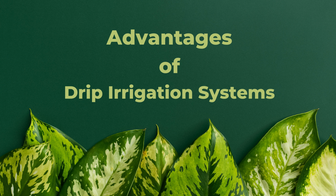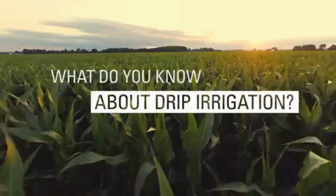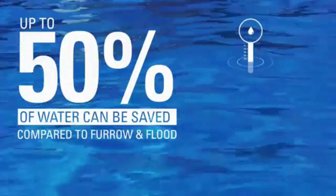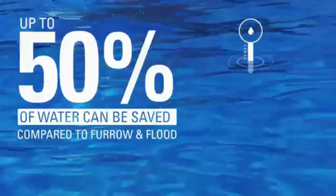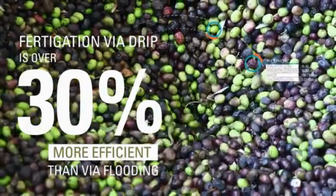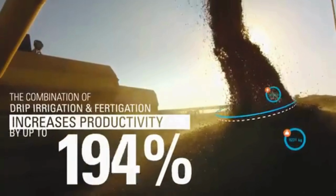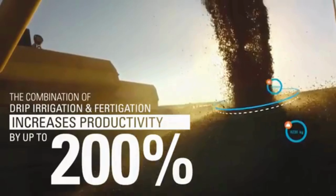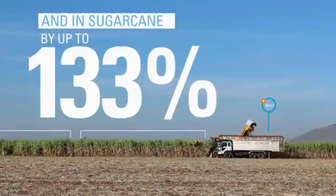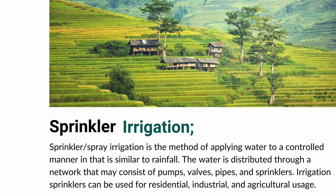Now you can see the advantages of drip irrigation systems. Up to 50% of water can be saved. Fertigation via drip is over 30% more efficient than via flooding. The combination of drip irrigation and fertigation increases productivity by up to 200%, and in sugarcane by up to 133%.